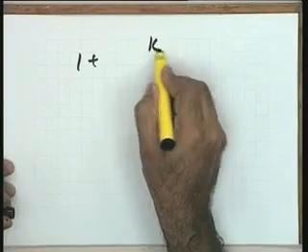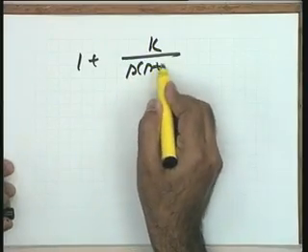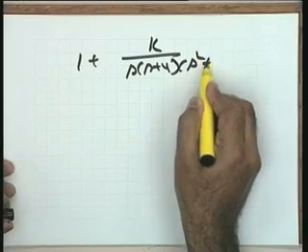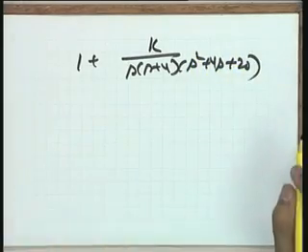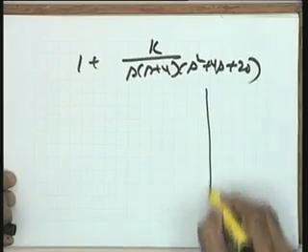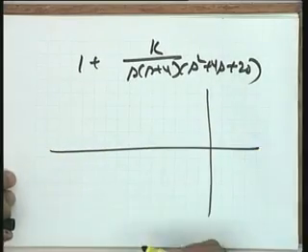Now, as far as the breakaway points, a little complex example I may take, the breakaway points necessarily are not the points on the real axis. Let me take another example. The example is 1 plus k over s into s plus 4, s squared plus 4s plus 20. Just to give you a passing comment, I am not solving this example fully, but let us apply the rules on this example.